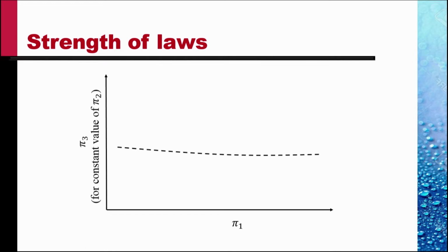We could neglect pi 3 throughout this region. Or the behavior could be like this, the solid line. Here we see the effect of variation of pi 1 on pi 3 is large. So we cannot neglect the effect of pi 1. Pi 1 is a strong law.